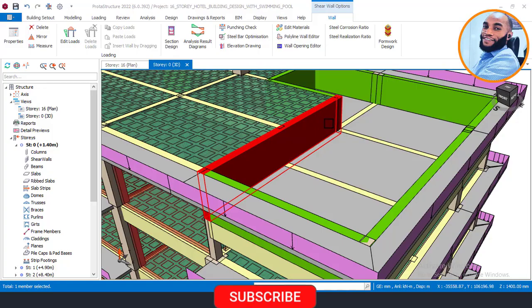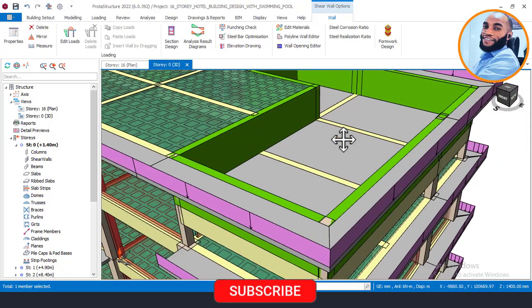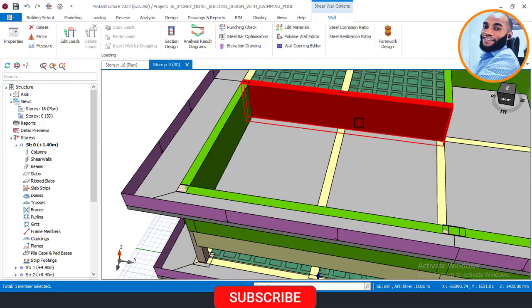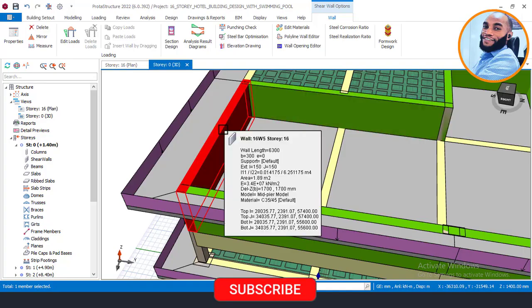Most of the time, when we are inserting wall load, once we have added one of the loads, we just copy the load onto every other one. But in the case of a retaining wall, you don't copy, you must define the load on each of the walls. So right now I'll come here again, click here and right click again, and then click on edit loads here.